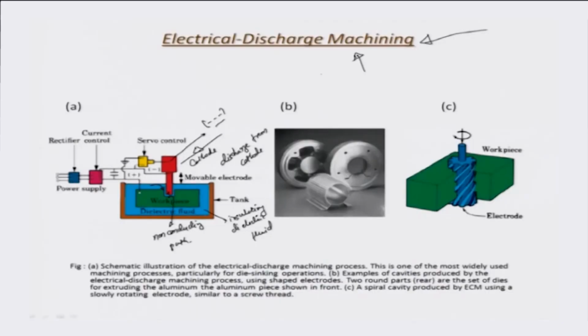So it is a useful tool, electro discharge machining, just as like electrochemical machining. Now I am going to give the details of the modeling process, etc., in later lectures, but here from a standpoint of what EDM can do, you can look at some of the components, high aspect ratio systems. Examples here are, for example, you can have these small cavities or these gearings produced by the EDM process or the electrical discharge machining process.